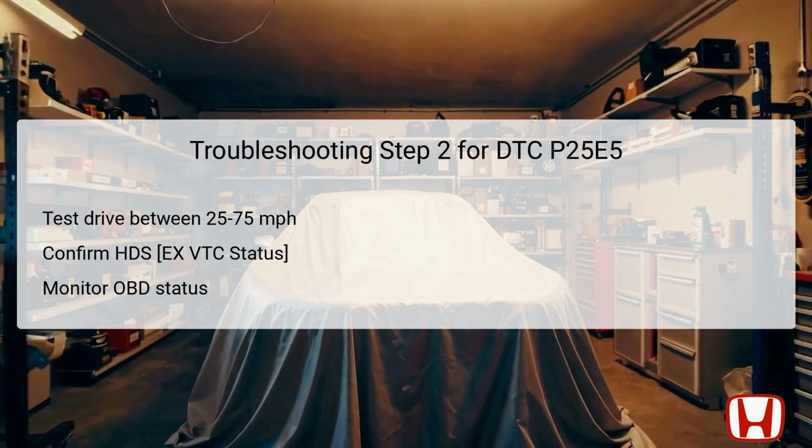Additionally, monitor the onboard diagnostics (OBD) status for the specific DTC P0014. This DTC is typically related and may indicate another underlying issue in conjunction with P25E5. Documenting all observations during this step will aid in the accurate identification of any failing components.